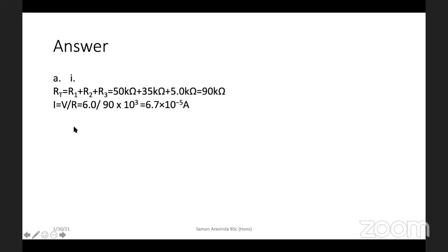So now you can find the voltmeter reading. You can just multiply this current value by the resistance across R. Or else you could use the potential divider method. But since we have the current here, we just multiply it by the resistance. So we get the voltmeter reading directly.